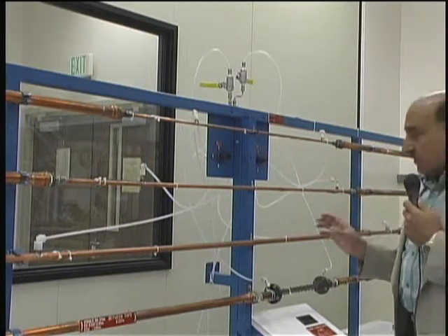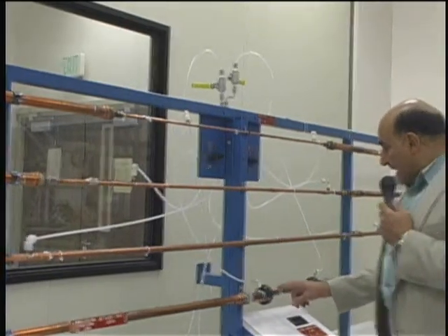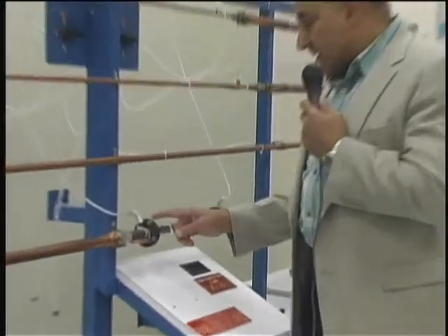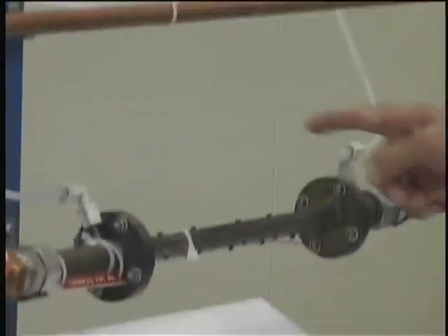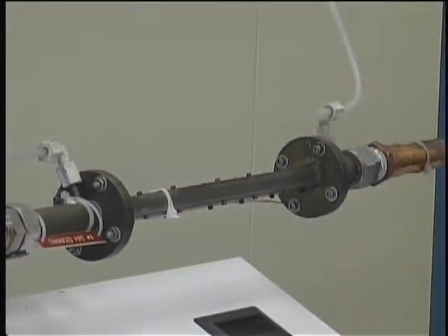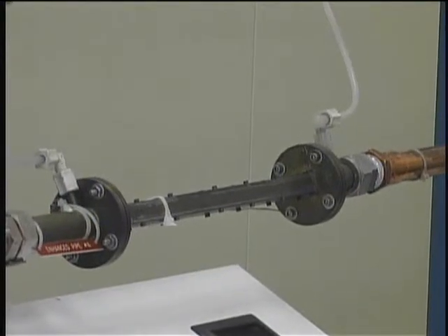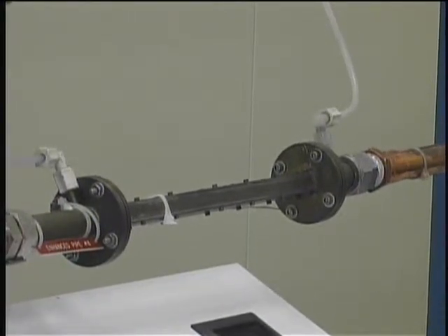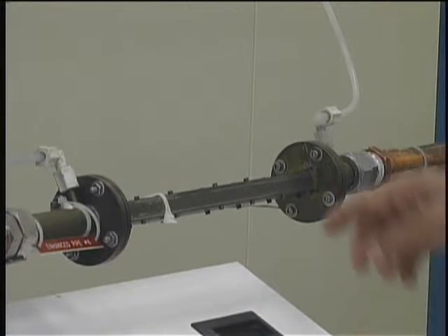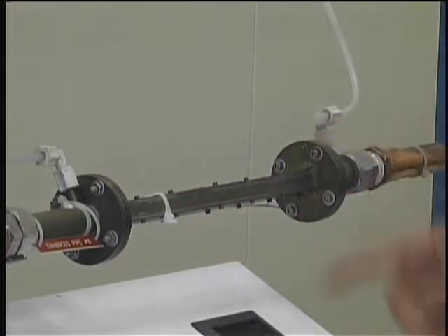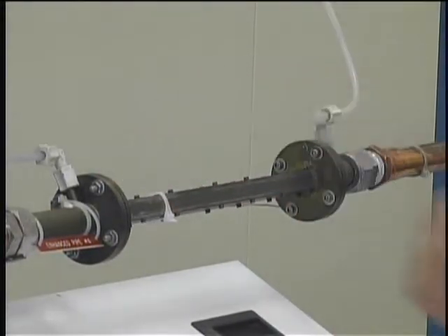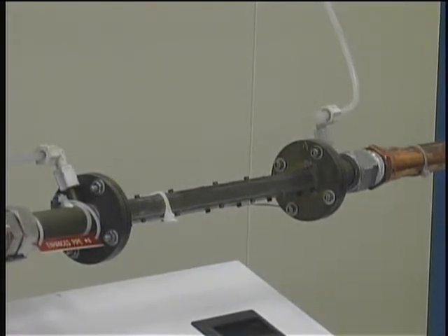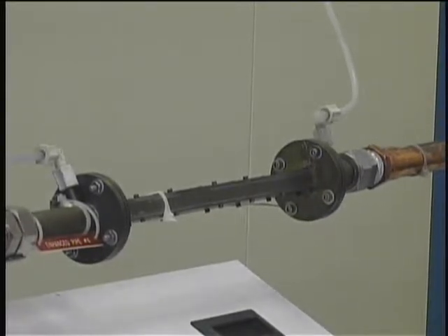Once we finish that, then we have a 4th pipe, and this pipe has a square cross section, as you can see here, and it has a short test section, and therefore the length here is 0.337 meters, so from here to here. And inside this pipe, there is a rough surface that is already machined to mimic the fouling that takes place in actual operating conditions in power plants.